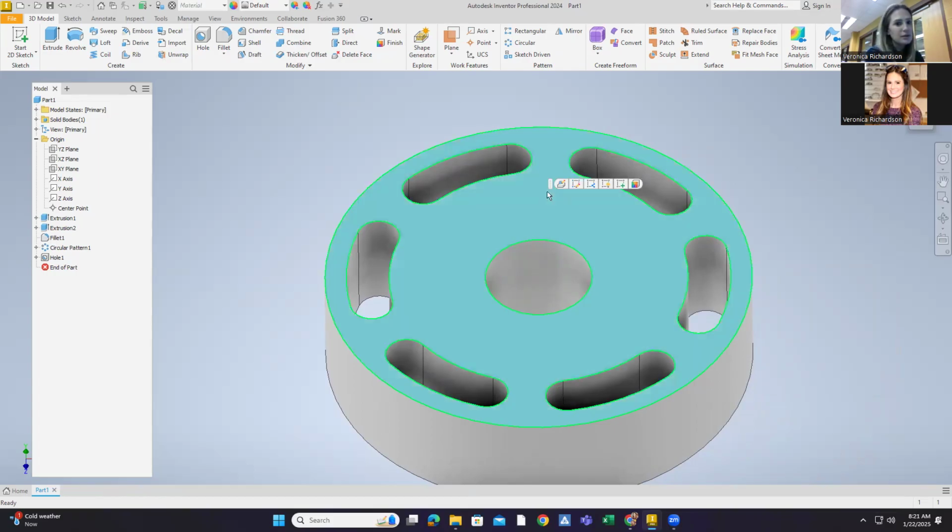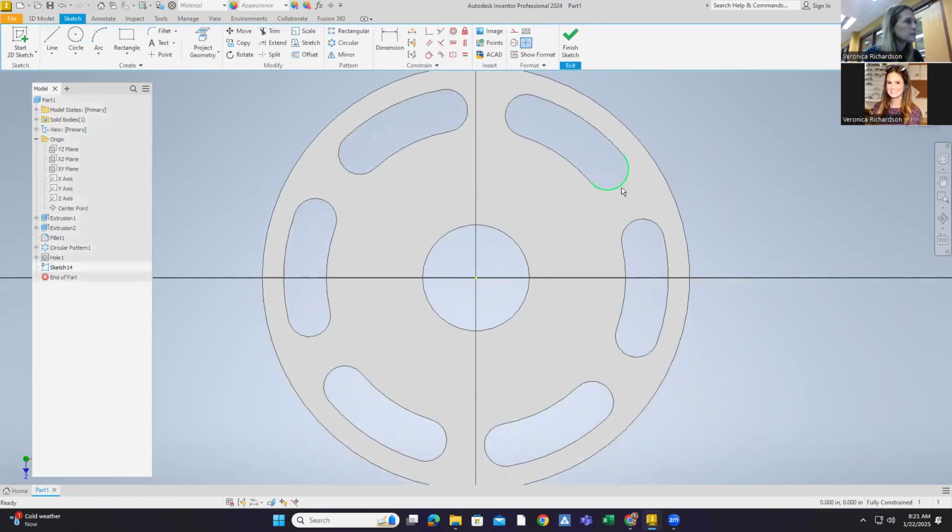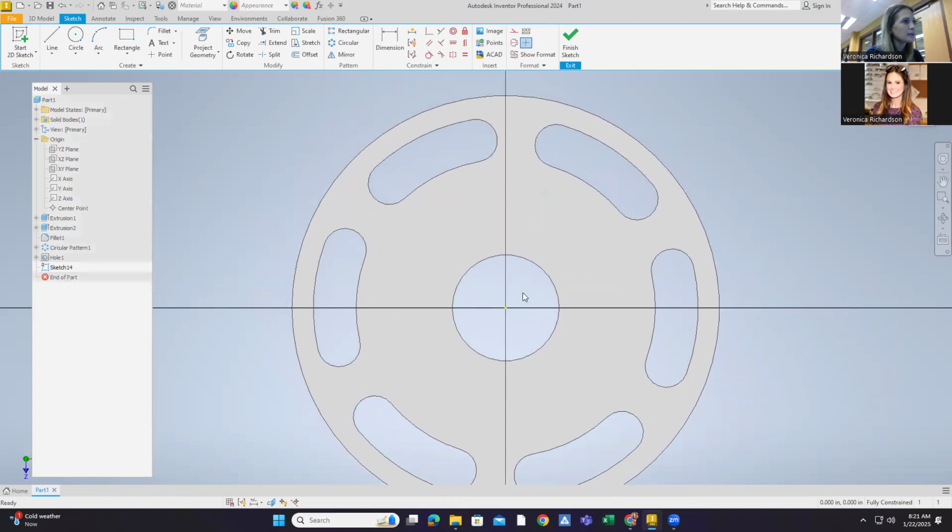You're just going to do a regular click with the left-hand side of your mouse. And create sketch is the one on the right-hand side with the green plus sign. When you hit create sketch, you should see those grid lines appear back on the top surface of your circle. You are now going to be using the circle tool.